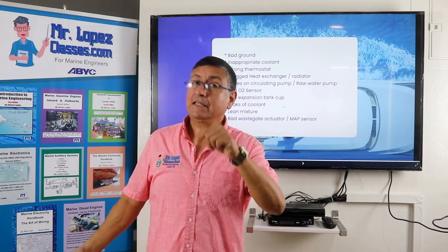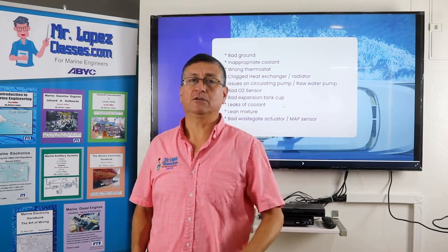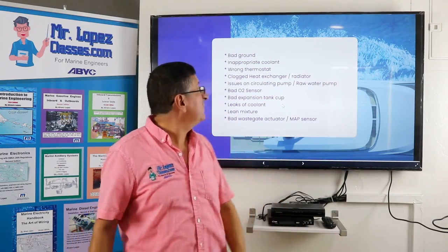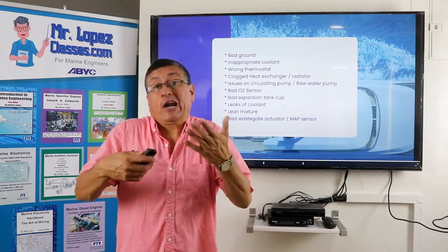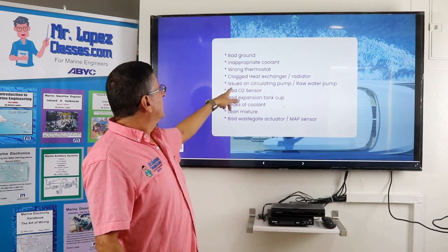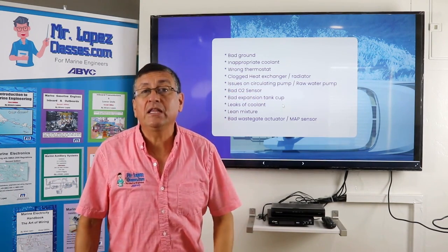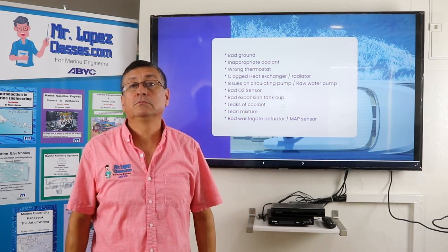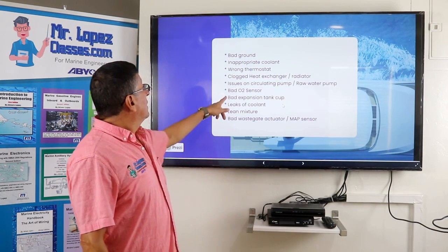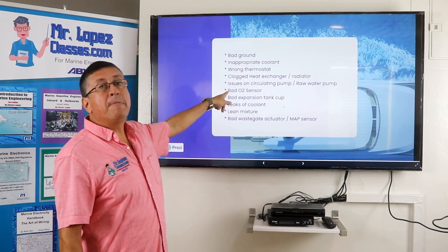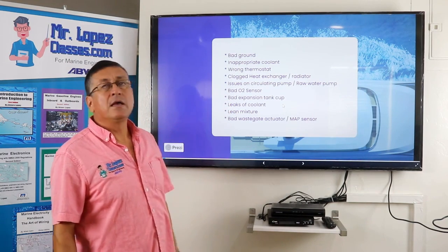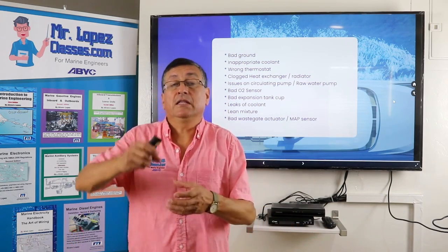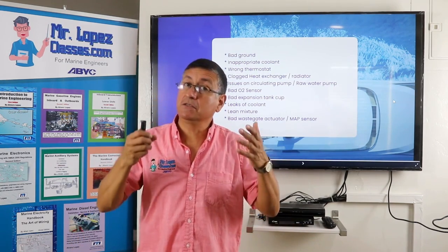Inappropriate coolant, don't forget, use the coolant recommended by the manufacturer. That's mandatory, that's important. A bad thermostat, that's possible. Clogged heat exchanger or radiator. Issues with the coolant pump or circulating pump or freshwater pump. Or a problem with the raw water pump also. It's very common. Bad oxygen sensor. Bad expansion cap, probably the radiator cap or expansion tank is bad.